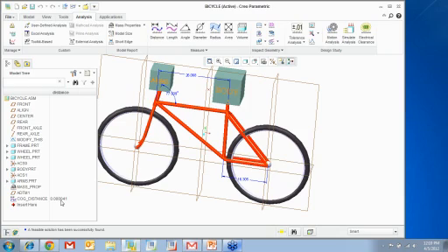If it's not, when the crankshaft rotates, it's going to induce a moment about the center of gravity position. So it's better if the center of gravity of that crankshaft lies exactly on the axis of its rotation. So we can go ahead and run a little math where the center of gravity is, then find the distance between the center of gravity and the rotation axis, and try to change various dimensions in order to minimize that distance to 0. So that's another use case where you can use behavioral modeling for, say, moving parts.